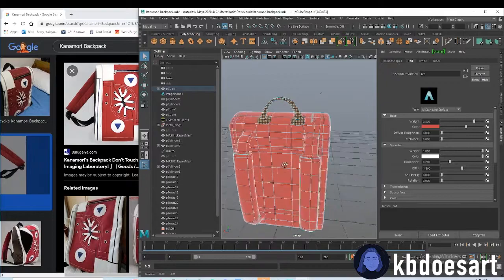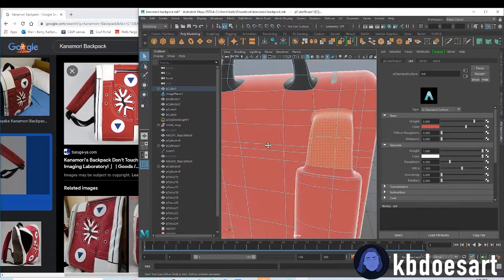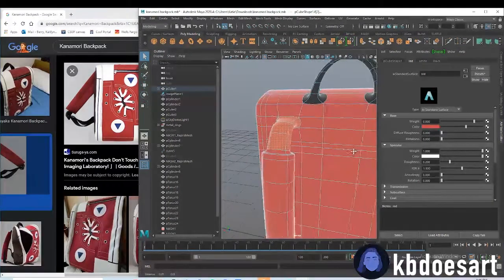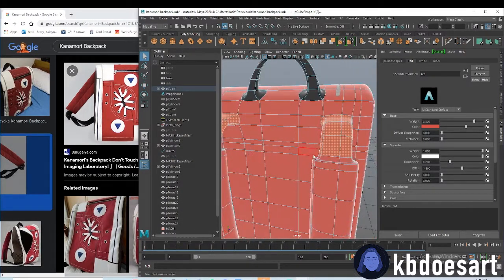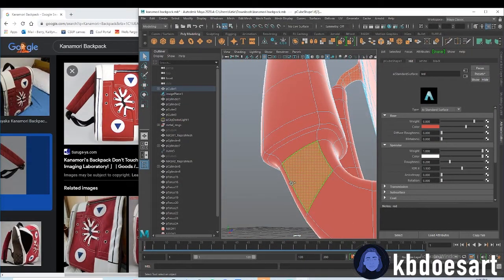And then it looks like also these faces should be black as well. So just select one holding tab and then double click the next one. Hold tab, select one, double click. I'll do those two. All right, and then let's do the bottom as well.